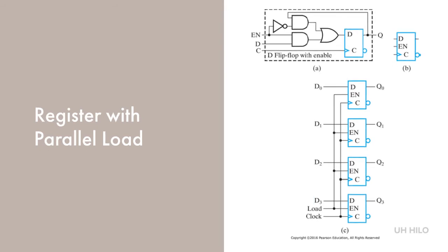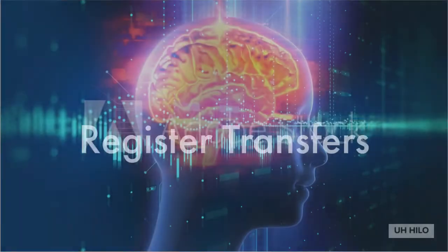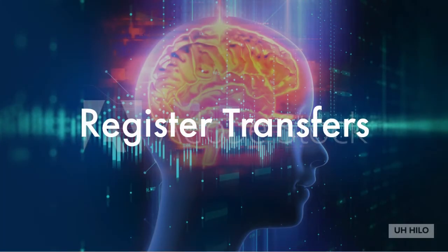The transfer of information from inputs to register is done simultaneously for all 4 bits during a single positive pulse transition. This method of transfer is traditionally preferred over clock gating, since it avoids clock skew and the potential for malfunctions of the circuit.